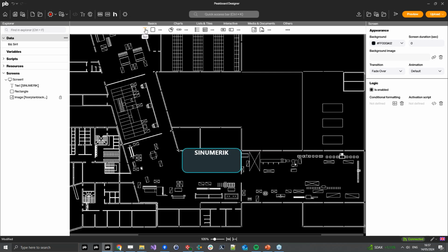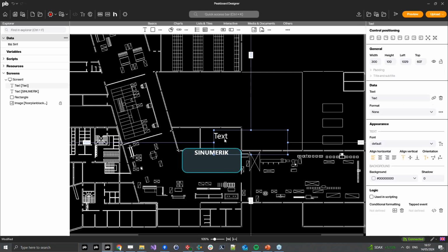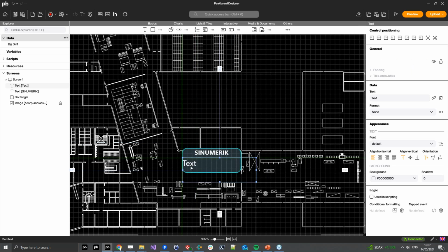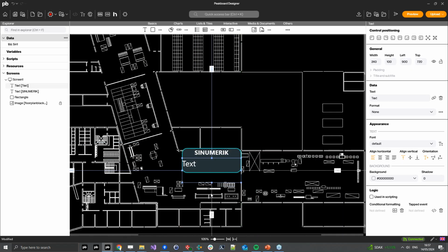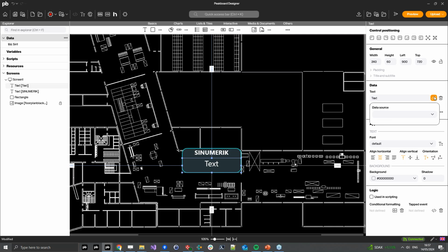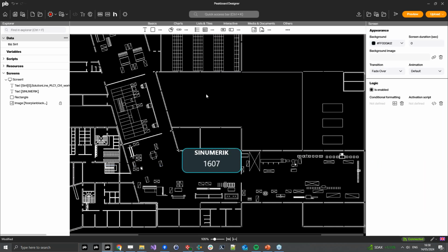So now I want to show the workpiece counter. Stefan already showed it on the edgeConnector side, and this one I want to show here in this rectangle. For this, I again centered the text, adding a text here from the top, and in that case, I want to connect this text to my data source. For that, I can just click here on this button with the chain. And in that case, I have just one data source, so that's exactly the one I will select. And I want to get the workpiece counter out of it. So here we have this data.